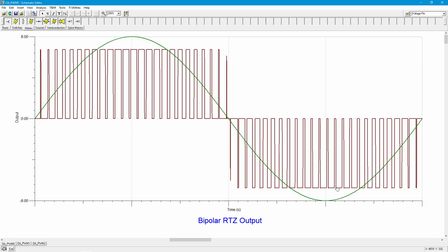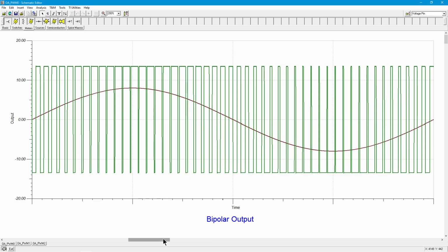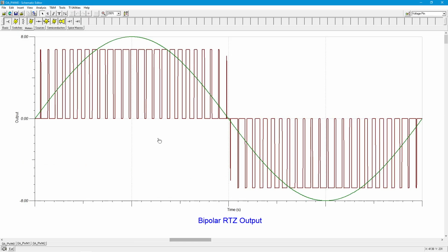But it's still the same thing. Big negative, big fat negative pulses. Sometimes, depending on how we drive the output devices, the transistors and so forth, this might be a more practical approach than this. It all depends on how you drive the transistors, because it might be that a big negative voltage over here could be damaging to the final output devices. So we create something like this instead. But still, the important thing is big signal, big fat pulse; small signal, you get a really skinny pulse.